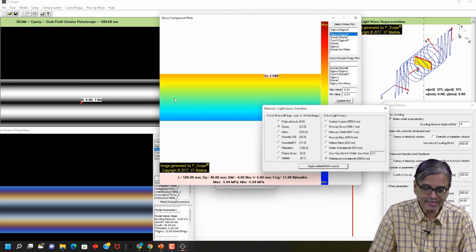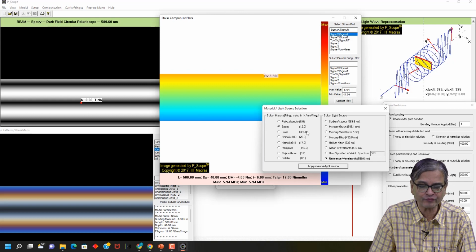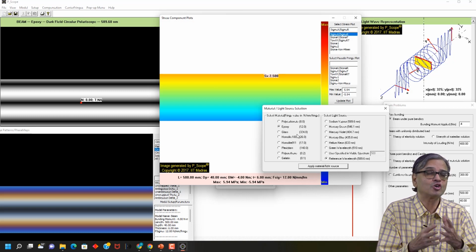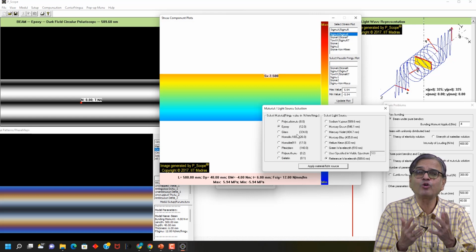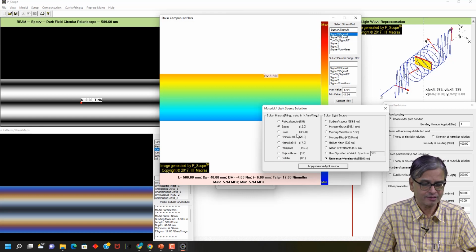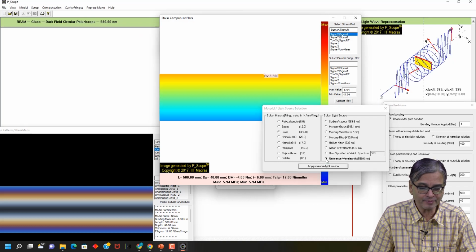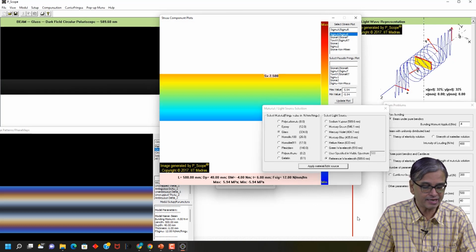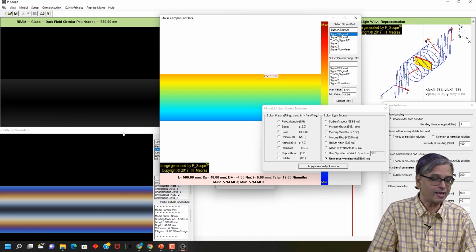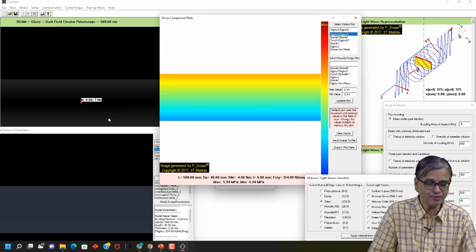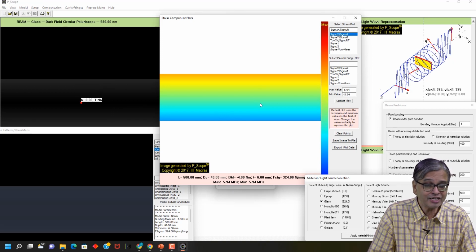You know, glass has a very high value of this photoelastic, that F sigma value. When it is very high, it means its response is very small. So, I am going to get something very close to 0 here. Okay. So, I have glass and then I put the material and then I see the fringes, what happens to this? I have this very close to 0. Has anything changed to the stresses?